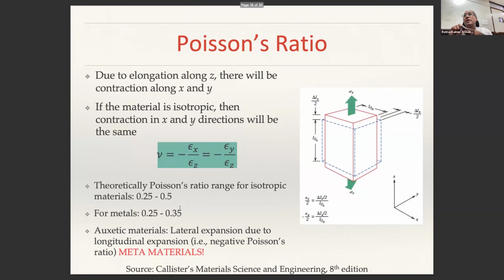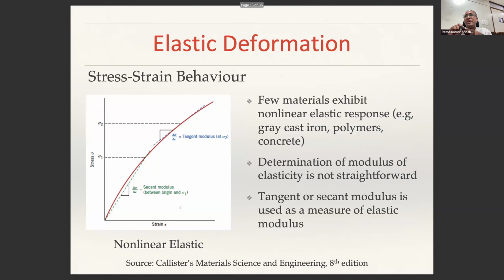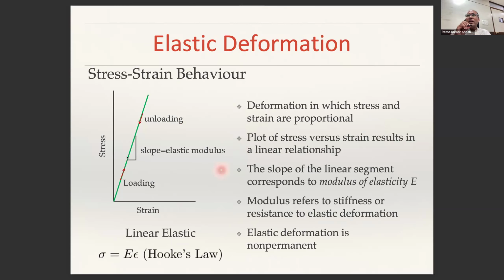As opposed to elastic deformation, wherein if you remove the load, it will go back to its original configuration. That means at zero stress, you will have zero strain. The reason for that is none of the bonds are broken. They are only stretched.